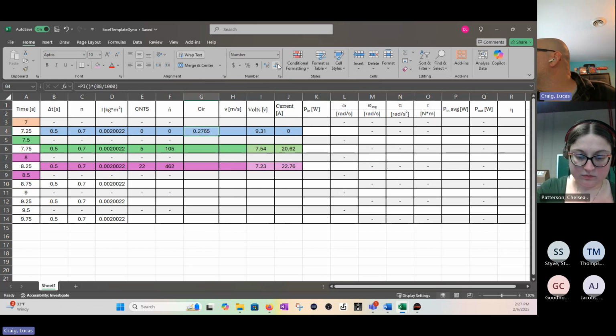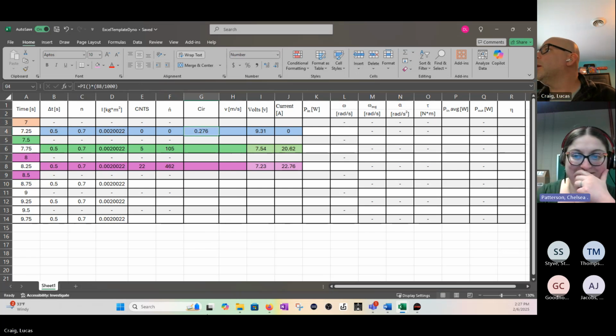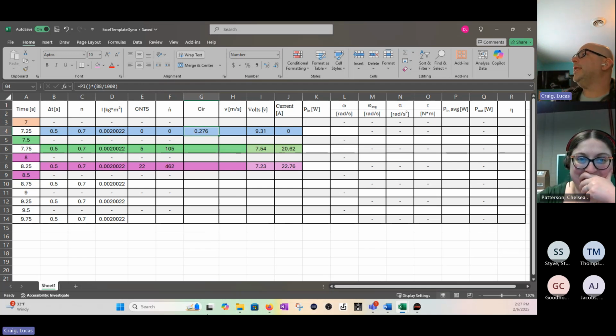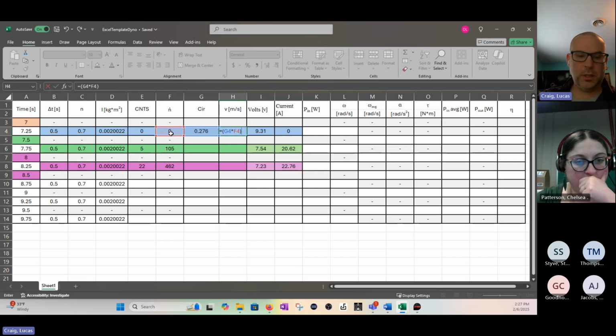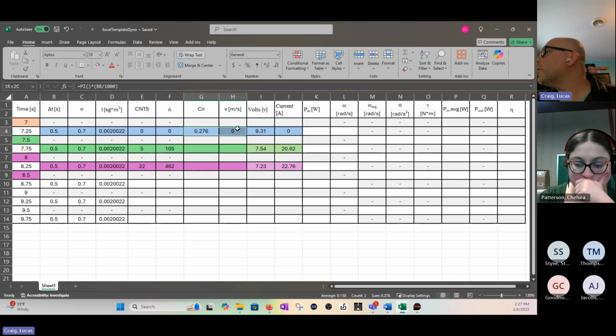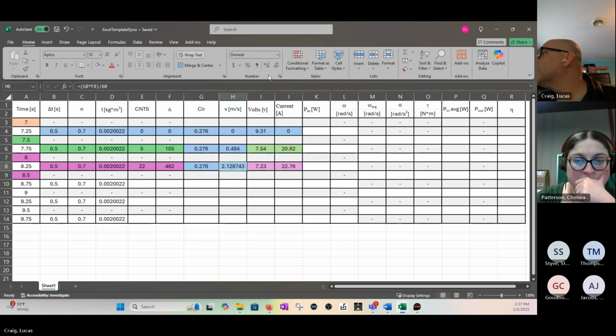Yeah, that's terrible. Look at that horrible format. Let's keep it like that. So it's just pi d. 88 millimeters is the tire diameter. And then, do you remember what the velocity equation was? That was circumference. So we're going to click, let's do parenthesis, this times RPMs, close parenthesis, divided by 60. And then I'm going to drag these both down. And that is horrible. Let's do 3 decimal places.